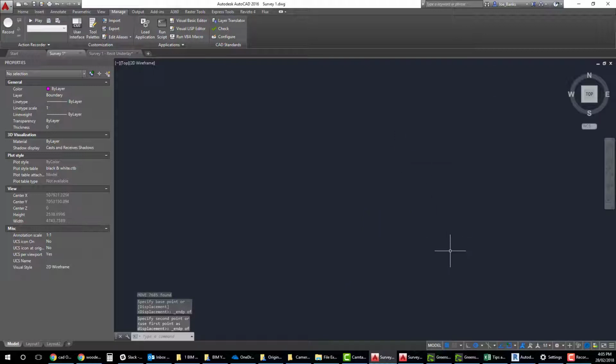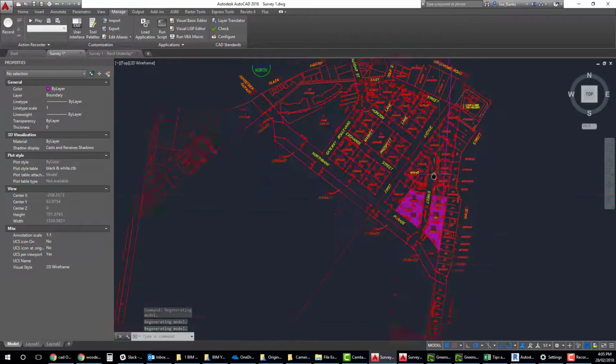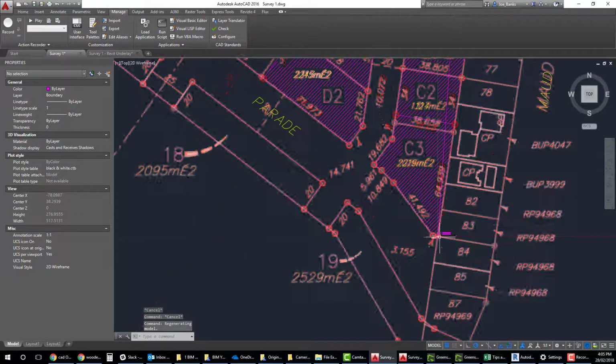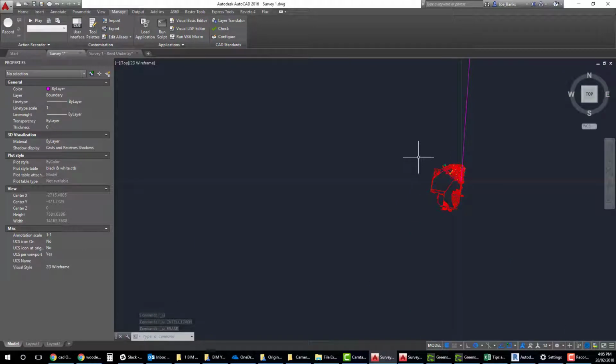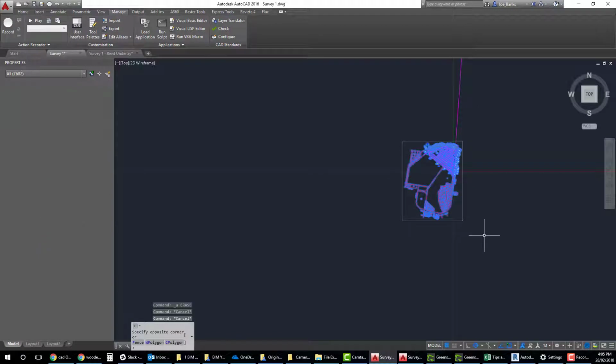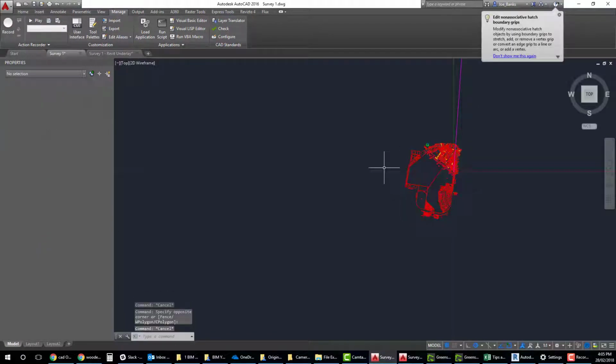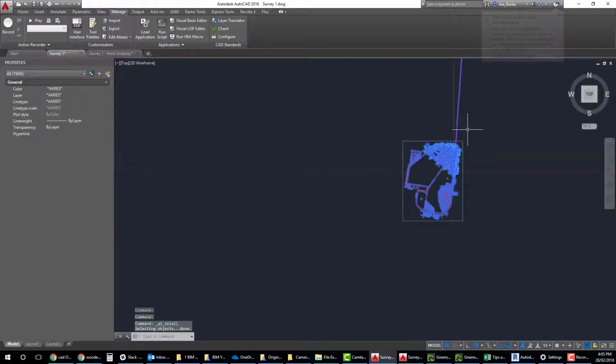Now if you zoom in here, you should be able to see that there's no longer anything at the end of this line. It's all now associated. So what we've done is we've made the CAD file origin 0,0,0 at this point, which is essentially our local origin, and then we've recorded how that point relates to our survey point. So now we just need to get everything to the correct scale. I'm going to click everything that's here. Actually, Control A, and going to SC for scale.